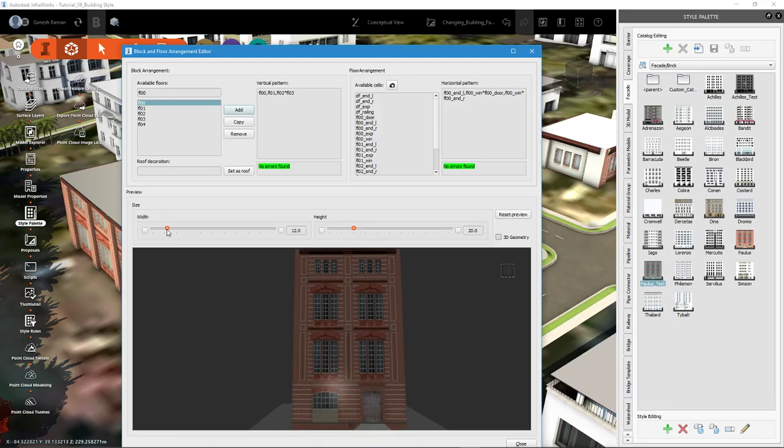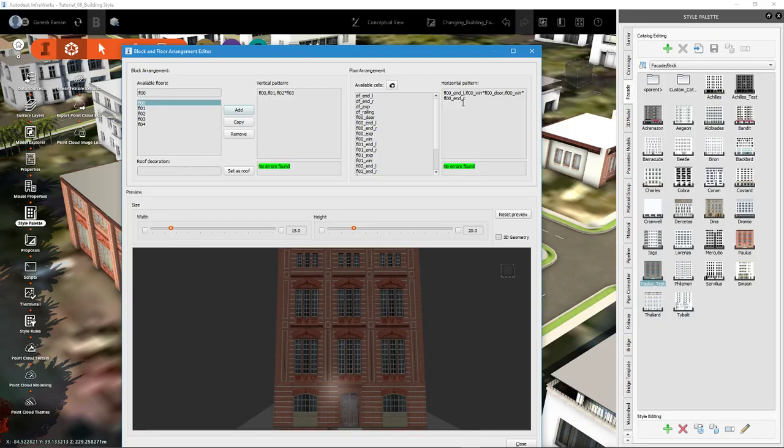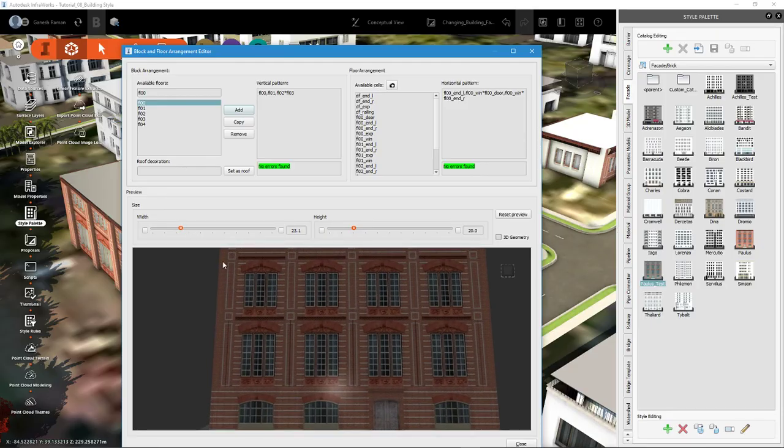And then I increase, so that code repeats on floor 0. At least one window and a door. And now there is more width available, so it will put, again, by precedence of the code, at least one window. So one window appeared. And when I increase, it puts another window. And at the end of the door, there is a comma, which means that after the door, there is not a repeating item of the at least function. There is definitely a window after this if the width allows. So it puts a window there.